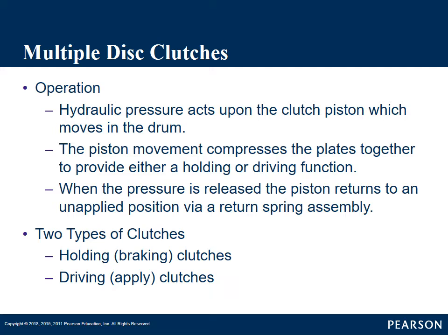so we're not trying to hold a clutch pack longer than we should. And then here it says that we talked about this, the two types of clutch packs. We have holding or braking clutches and driving clutches. Remember, we have to hold one of those members of the planetary gear sets, and then we need to drive or apply another member of the planetary gear sets, and then the third member gets turned into our output.